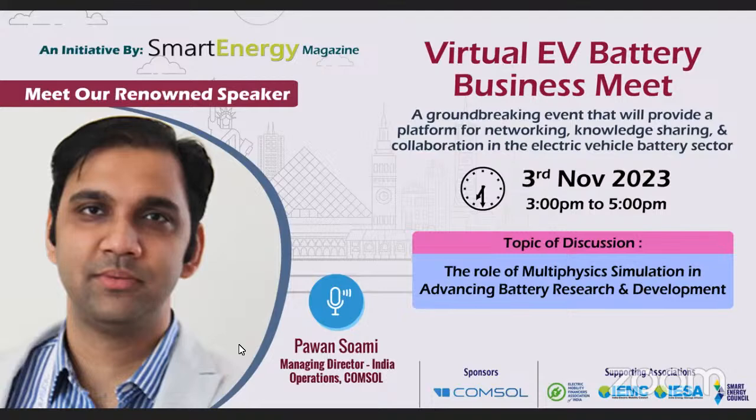Now you are interested in how the high current will propagate in other cells, or, because there's gas venting, how the heated gases coming out of the cell will affect the other cells' temperature. Or it may also trigger thermal runaway or any other failure in other cells. So everything can be simulated. It depends on how much depth you want. Those many inputs will be required.